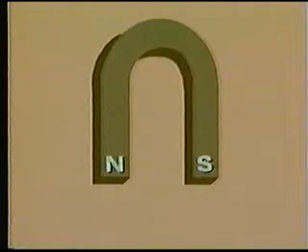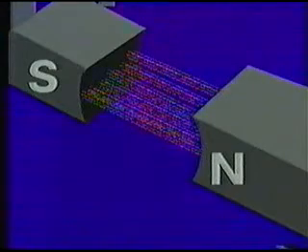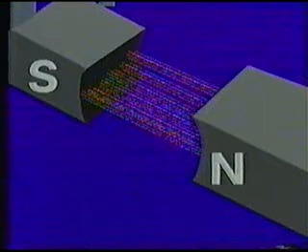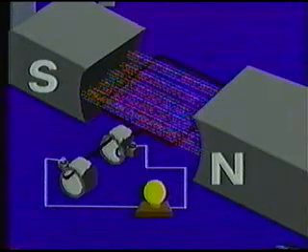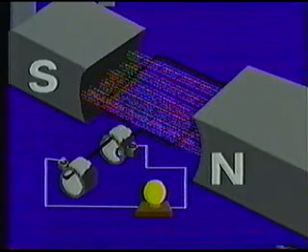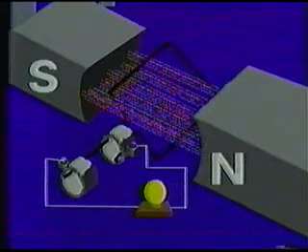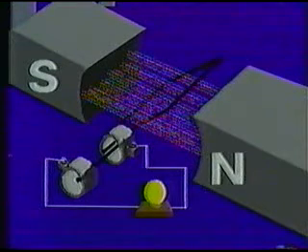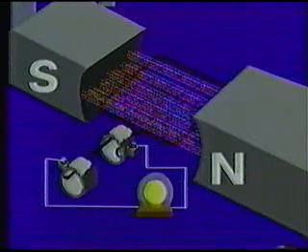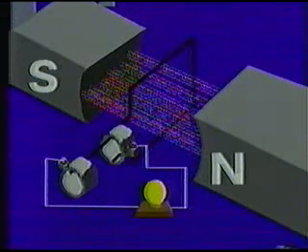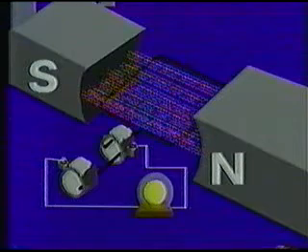Between the two legs of this horseshoe magnet is an invisible magnetic field. This invisible concentration of magnetic field is called flux. Suppose we consider these lines of force and how we can use them to create electricity. Let's add another component so that we can begin to use this potential energy. This conductor loop, when rotated by some mechanical means, will cut through these flux concentrations. Each time it cuts through this flux, a small induced electrical voltage will be generated in the conductor.